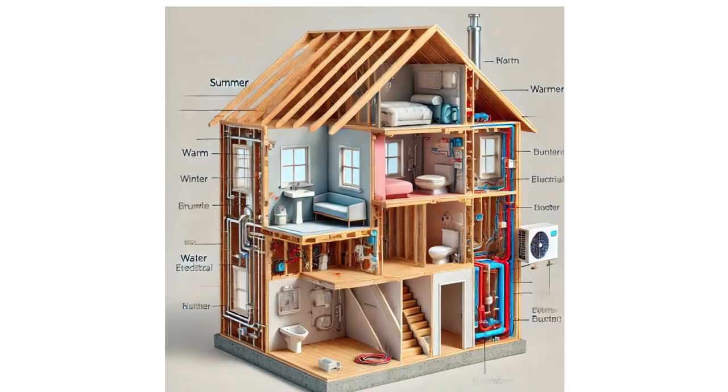Here we've got this somewhat horribly drawn image. It's an AI image. If we look at the home, we can see some elements of structure. So we see up in the roof, we see here the rafters. We see right here these 2x4 studs that are inside the walls. Here we've got the floor joists. Okay, these are the beams that hold up the floor.